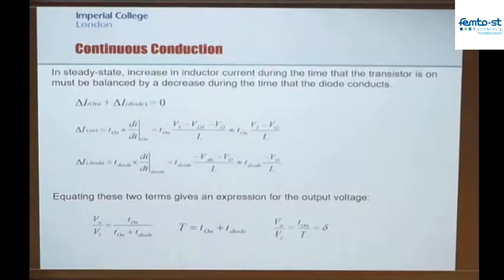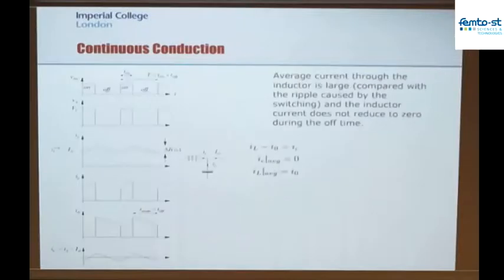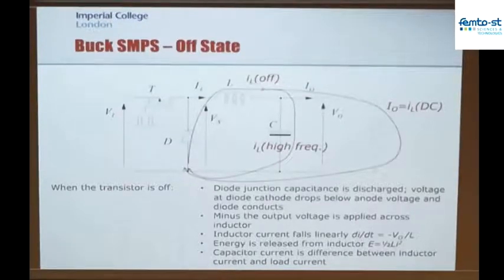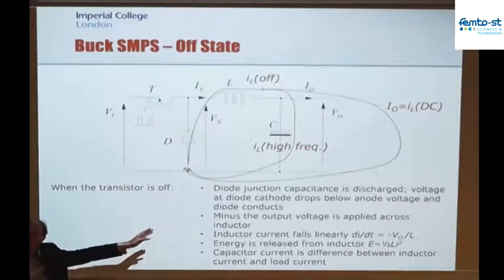The previous supply, the linear regulator, had losses that were not just about the implementation. The losses were fundamental to the approach. So that basic principle of taking this type of circuit, creating an AC waveform by switching this device fully on, then fully off, then fully on, then fully off, and low-pass filtering it, is what gives us this capability of power processing in a lossless way and converting one voltage to another.